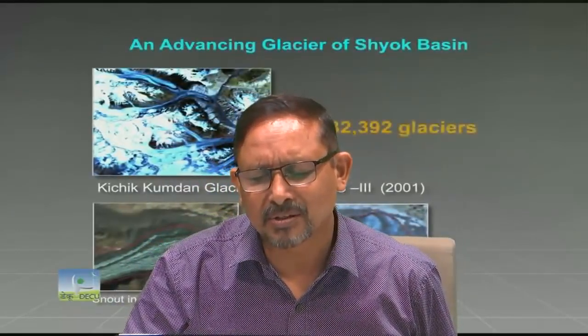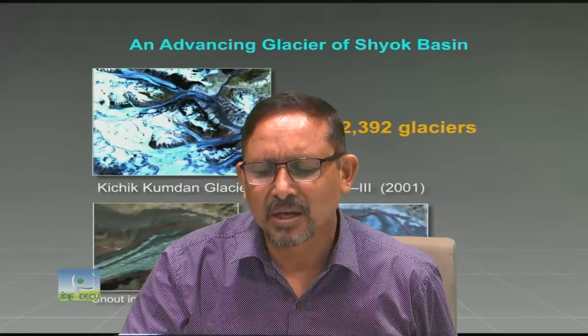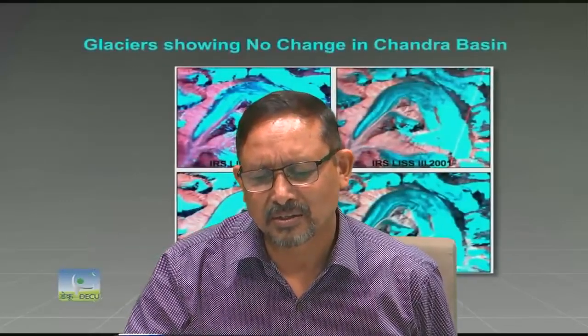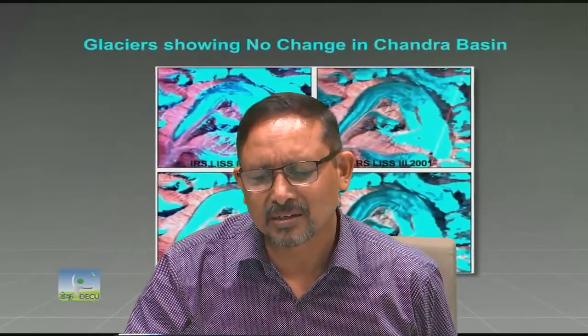There are two numbering systems, as I told you: Strahler and Shreve. Strahler is the most commonly used numbering system, which is used in India for assigning first order, second order and third order streams, and for watershed characterization. So you can go for the Strahler ordering system.